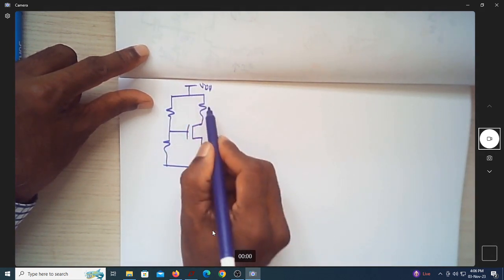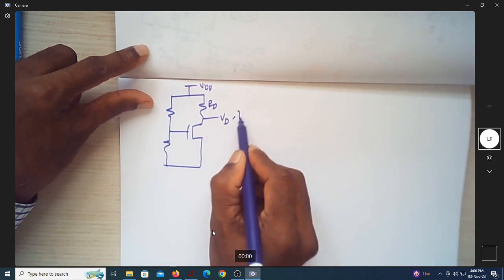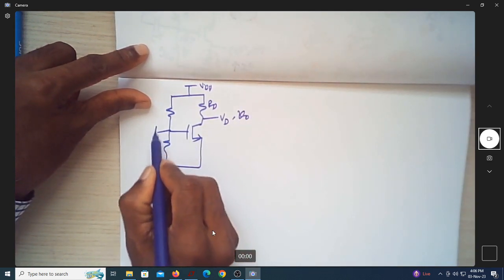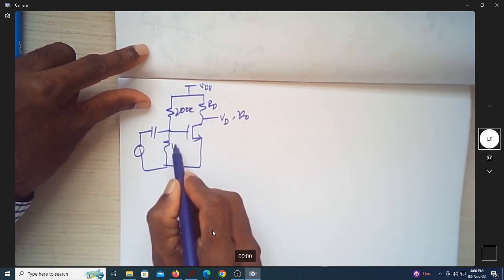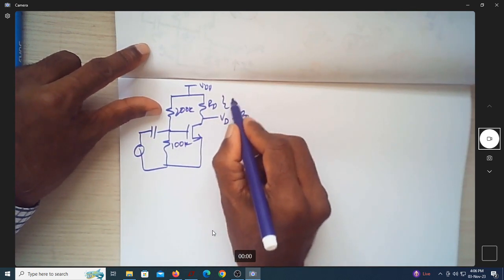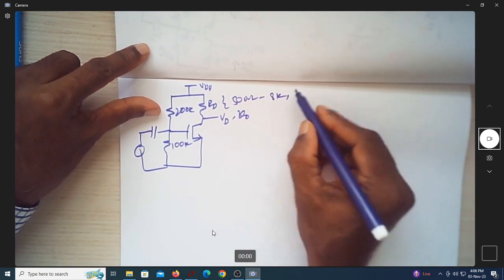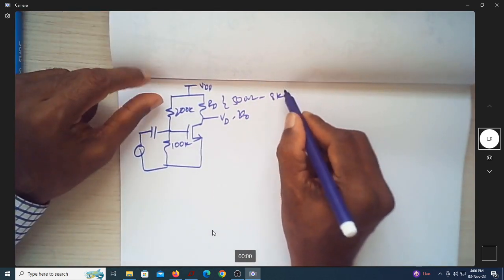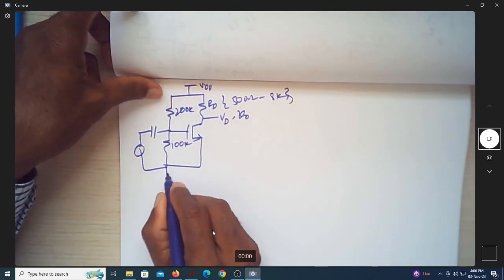This is VDD, this is RD, this is VD, that is DC, and this is V0 output. Let me have this as 200k and 100k constant. Let me vary this from maybe 500 ohm to maybe 8k, with an increment of course you can give randomly, or you can let us just decide what will happen. So what is expected here,